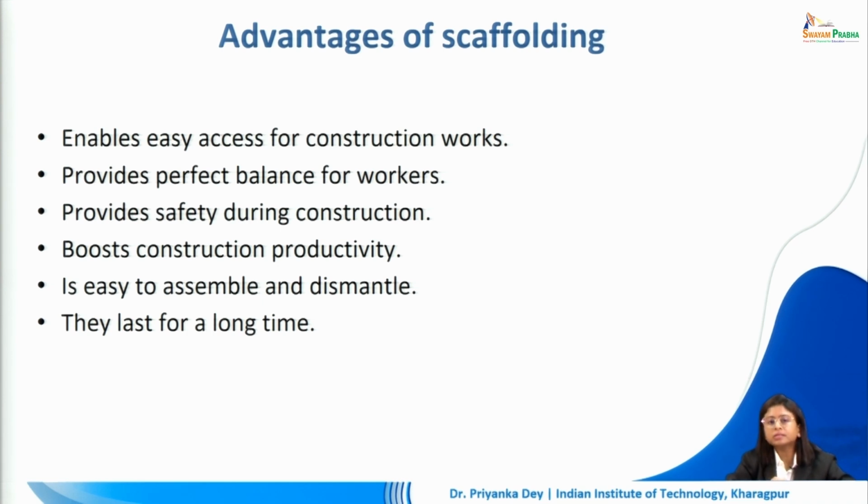Definitely because of this, it boosts construction productivity. Otherwise, it would become very difficult, and it would also make it hard to get good finishing of all the building parts above 1.5 meter. To ensure that the finishing is good, that we maintain levels and the proper look or aesthetic is maintained, we need to ensure that we provide them a proper working platform.